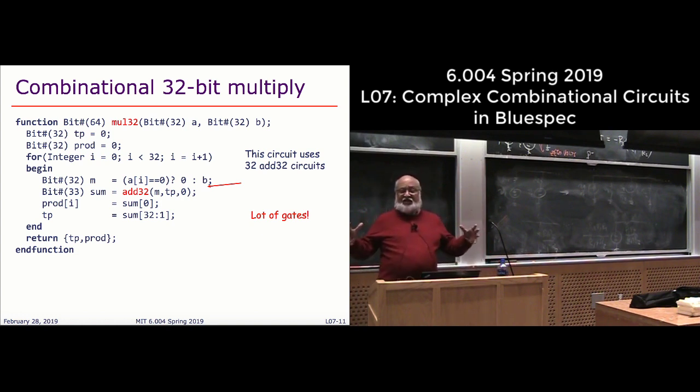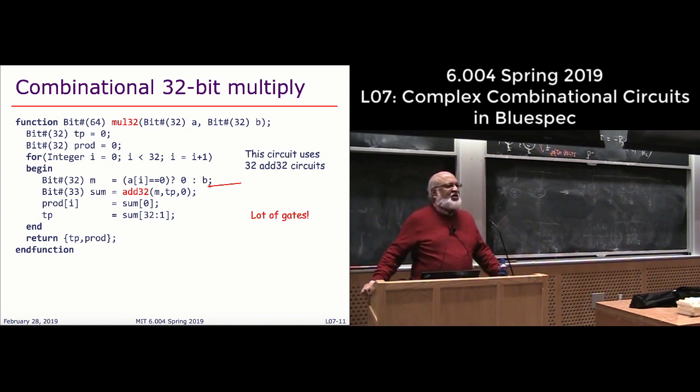The adder had so many gates, and now we are freely using them, and you'll love the power of parametrization. You say, ah man, I could have designed a 64-bit one also. No extra time, no extra charge for you. But what you cannot forget is if you designed a 64-bit adder or a 64-bit multiplier, that circuit is dramatically larger than the 32-bit circuit.